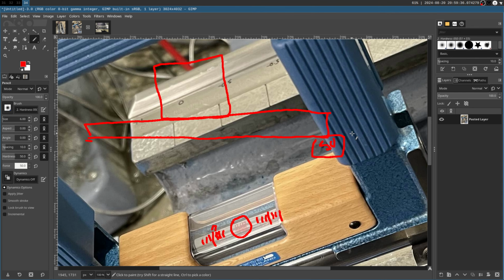Do you get the same measurement when flipping the dumbbell around? Yes, that's actually how you calibrate levels. And that's another reason why levels are fantastic: you don't need a level surface to calibrate a level. You take a level, you set it down on a flat surface. It is important that you can reproduce the flatness, obviously, of the surface.